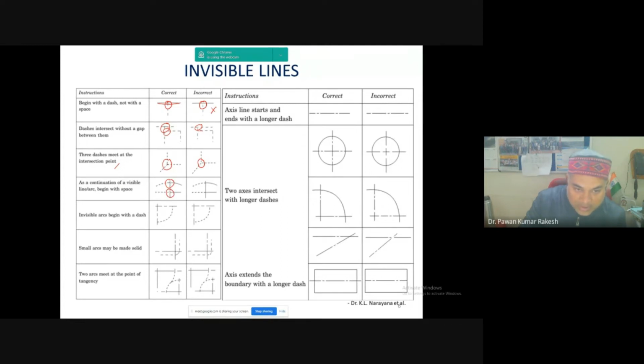This part is part number one, and this part is showing the other part of the object. So this is part number two. Or if you want to show any symmetry, in that case you have to make it a hidden line. So this is the real object. You must follow a certain gap between the real object and the hidden line parts. So here you can see this is not making the space.